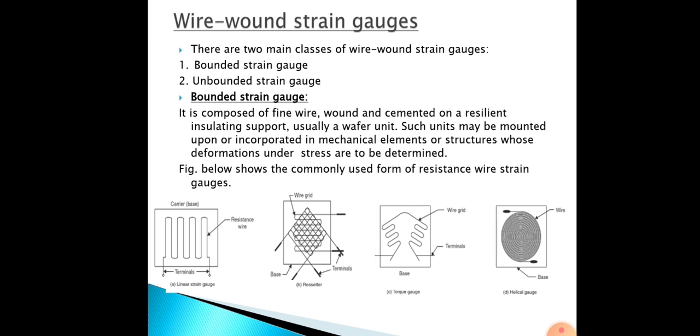You can see over there, these wires comprise the four arms of the Wheatstone bridge network, of which two opposite arms are tightened and the other two slackened by the displacement. So two arms will be tightened and two will be slackened, depending upon the movement.